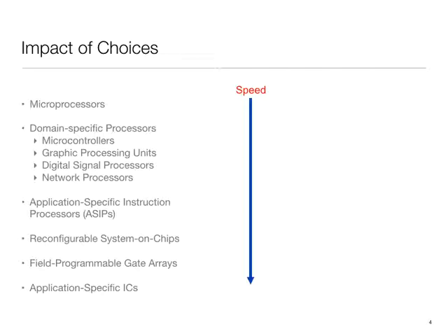So speed, you'll expect better. Power, you will expect this side to be better, so power or energy goes up out here: less efficient, more efficient. A good rule of thumb is that every time you specialize, going from microprocessors to FPGAs, a 10x, and going from FPGAs to ASICs, another 10x loss in performance or power efficiency.